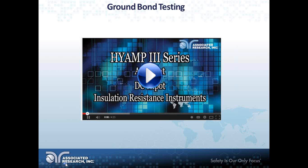And you also saw I performed an offset on that unit as well. Most ground bond testers out there these days, ours and competitive units, have offset features. They realize that sometimes you have long leads, or if you're on a production line where you have long spacing and a lot of cables, you might need to offset those numbers. So you can certainly do that and then run your test. So that was an example of a ground bond test.